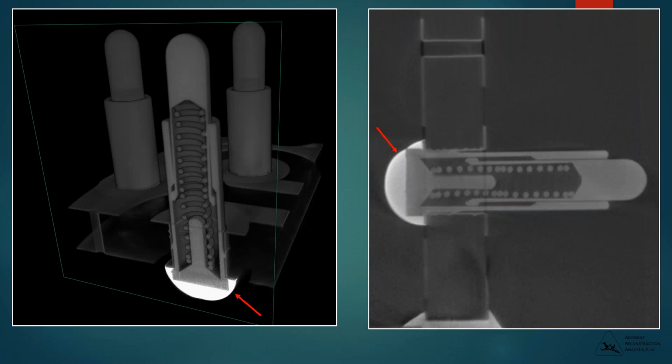Here's an example of small pins from an electrical connector, both compressed and decompressed. In these, we were mostly looking for solder penetration. They're pressed through a circuit board, and the client wanted to know if the solder was adequately penetrating the through holes. A couple of things to point out: the overall length of these pins is about 6 millimeters.